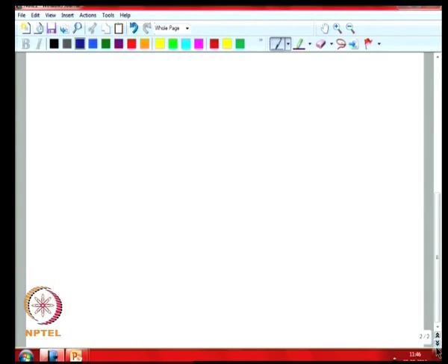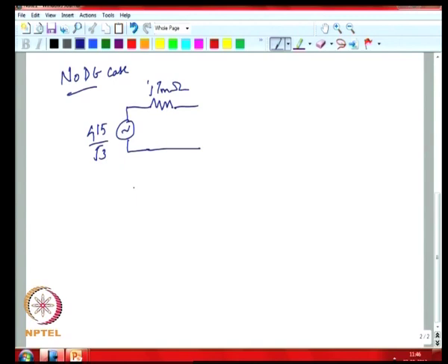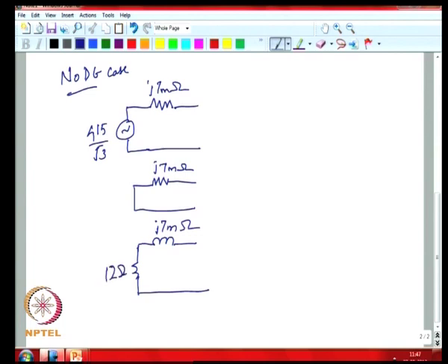We will look at the situation when there is no DG connected. So, if you have a single line to ground fault, your equivalent sequence network would be, and your source is grounded through the earth impedance coming in between, which is 4 ohms.